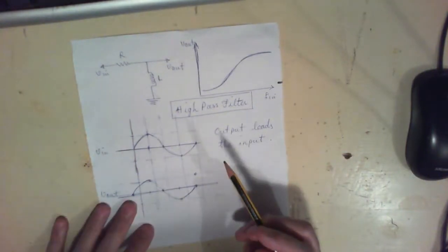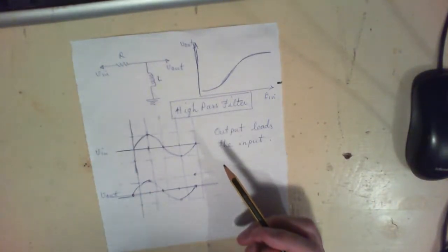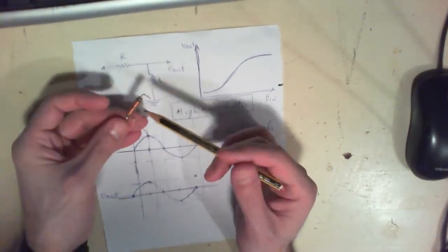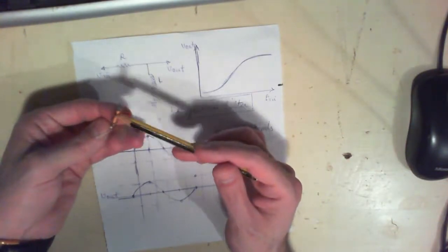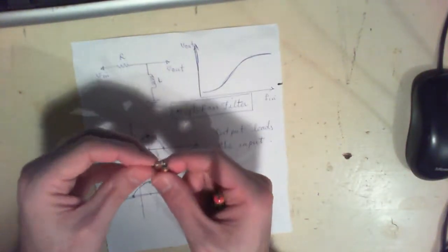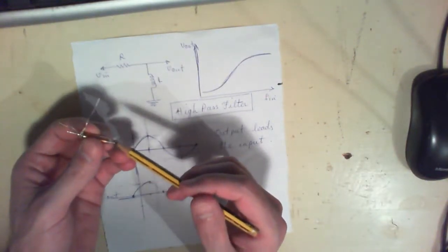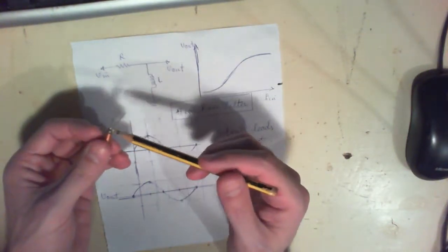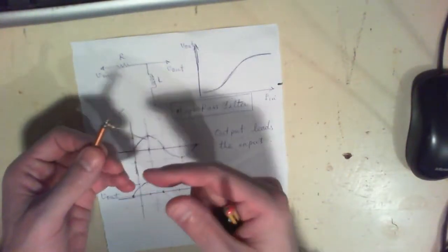The circuit that I want to use here has a resistor and an inductor. This is my inductor, and this is my resistor connected in series with the inductor. We will inject the signal into the resistor here, this lead over here becomes the ground, and the lead where the two components are tied together becomes your output, referenced to the ground.